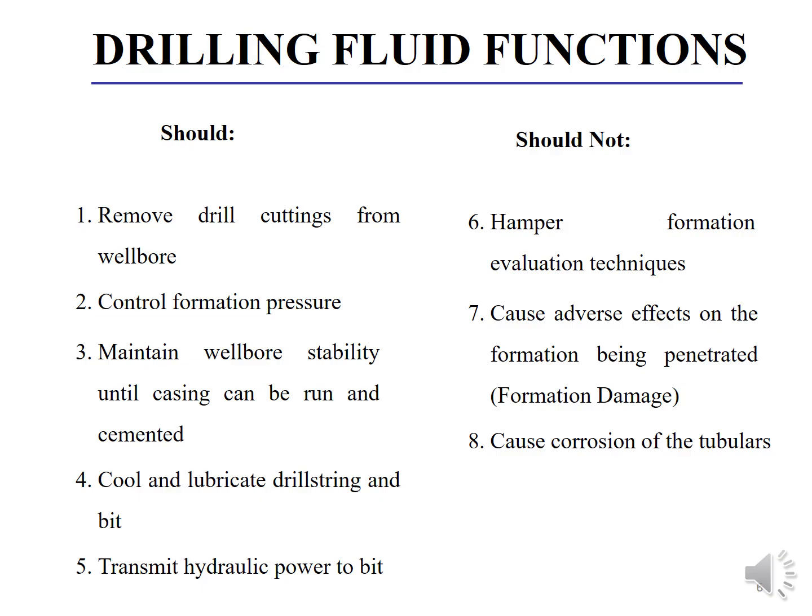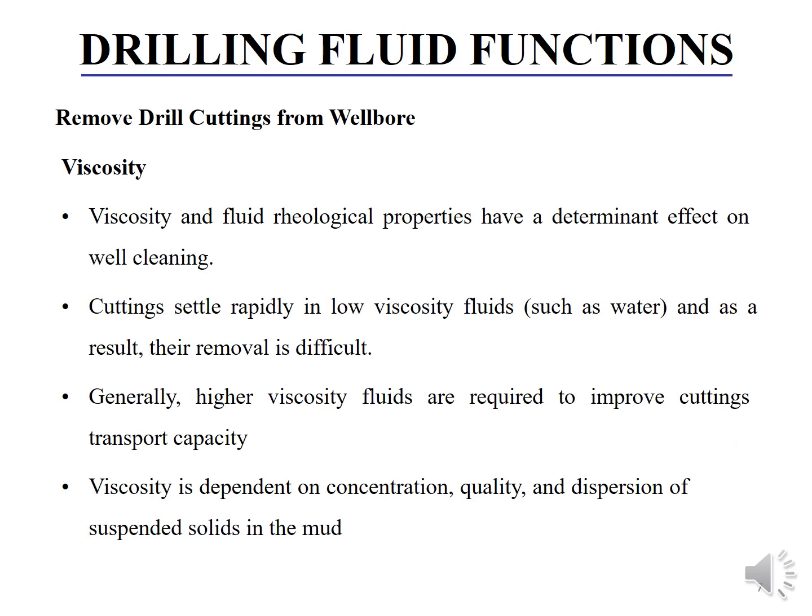Then cool and lubricate the drill string and bit, transmit hydraulic power to the bit, and it should not hamper formation evaluation techniques. It should not cause adverse effects on the formation being penetrated, that is, formation damage should be avoided. Then it should not cause corrosion of the tubulars which are inserted inside the drill. Then it should remove drill cuttings from the wellbore.